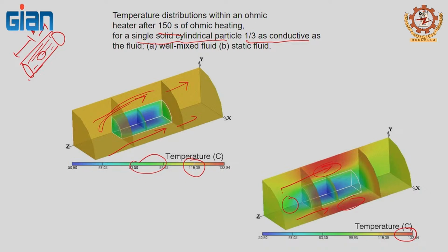So, the point here is, in the ohmic heater, if you have a change in electrical conductivity between the liquid and solid, you could have different heating in the liquid and solid, and then you are going to have a non-uniform temperature distribution. When you have non-uniform temperature distribution, that means you are not going to heat the entire mass the same as we originally thought possible. That means you are going to potentially have microbes there. It's potentially a food safety problem.